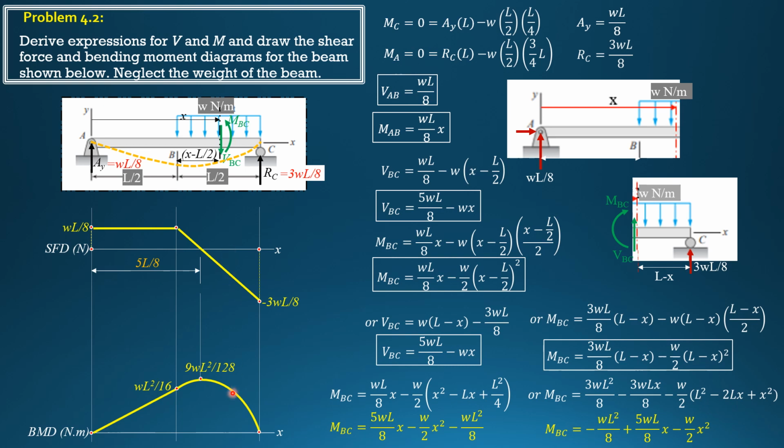If you're still confused, then it is mostly scaled plotting so that you will have a correct moment curve. So you just plot intermediate values like 3/4 of L, then 7/8 of L. 2 points are enough, or even 1 point is enough. You evaluate this value here, and that's it.